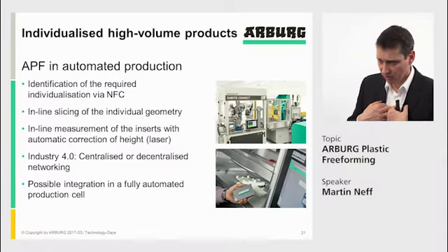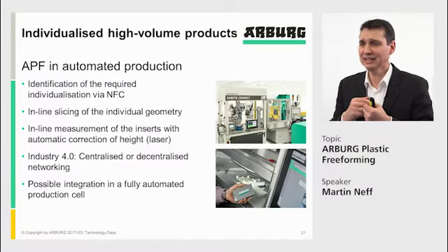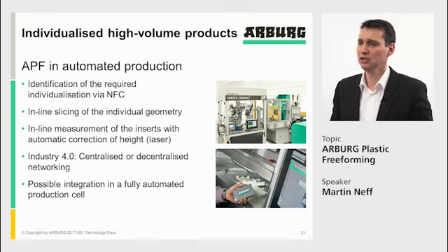And as I said, an injection molded part gets individualized in that way, and we are even going down to piece production number 1. In that luggage tag, we have an NFC chip with several different data, also the whole production data. Internally there is the chip. From the freeformer side, we do inline slicing of the individual geometry.